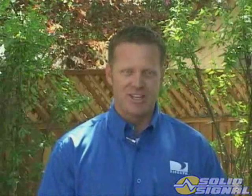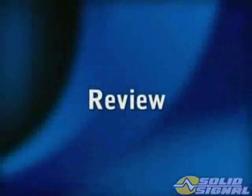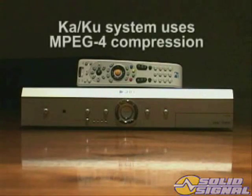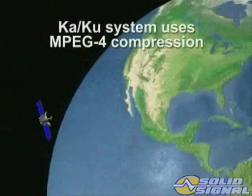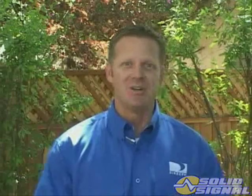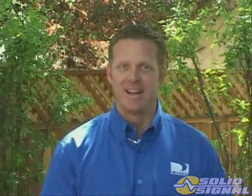Alright, we've covered a lot of information in this video, so let's take a quick review. The KA-KU system uses MPEG-4 compression. This means we can send more digital programming in less space, so we can offer more high-definition channels than any other program provider. This new technology uses Ka-band satellites that have higher downlink frequencies than our current Ku-band satellites, eliminating the possibility of them interfering with each other.